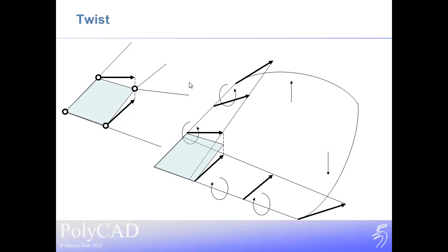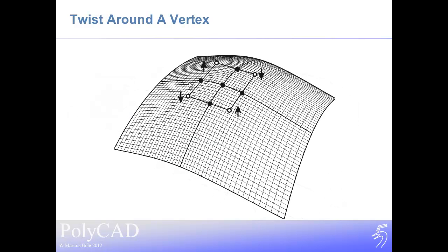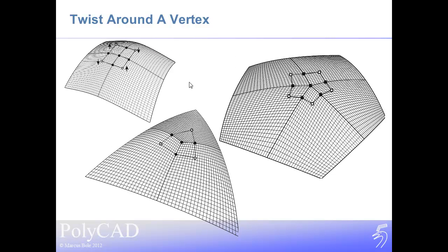Now this scenario is only working here for one surface in a corner. This happens at a vertex which could be part of our multiple patches. Now the limitation here is for a four-sided surface, for example, we need to connect up those corner vertices so that they're all in alignment to ensure that we have complete tangent compatibility. This arrangement gives us a little bit of manipulation. We can think of this rectangular structure as a linkage where we can shift a point up and its opposing points will go down, but the linkage will follow through. For an odd number of patches around a vertex, to achieve that same linkage means that we've practically got to put all the points on a plane. And that means that again we don't have the flexibility of the surface tangent as much as we previously wanted.